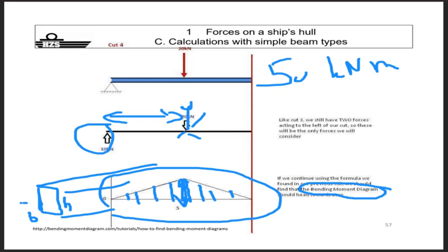But here, the neutral axis is perfectly in the middle of your beam, because if you take the area center of gravity, it's in the middle here. Yeah? Where do you have the highest stresses when it's subjected to bending? So it goes like this. It's sagging, yeah, then your stress level will be like this. Compressive, tensile, equally divided over positive, negative, because it's fully symmetrical.